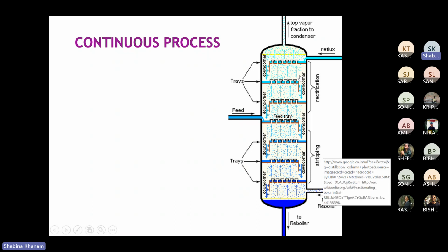And because of that, to ensure that, we need to consider the vapor flow in such a way that it always keeps liquid over the plate and does not allow liquid to move down. And once the liquid moves down through these holes, we call that the weeping condition. So weeping is also a part of the design, and it should be avoided.